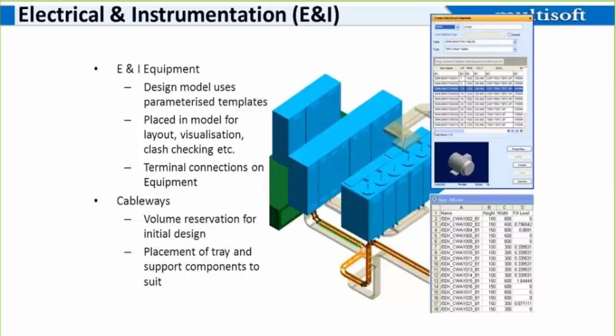Cable trays can be modeled. Again, volume reservation can be done using the cableways. Cable tray supports can be modeled here. Again, these cable trays are catalog driven and can be modified as per the project standard.